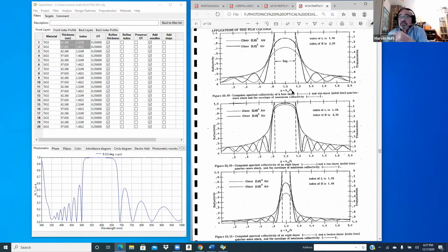We're saying that it doesn't matter, just like the quarter wave layer is a symmetrical V like this, one quarter wave. 2 quarter waves is like this, okay, symmetrical around G equal to 1. So this is really phase, okay? Because the phase is 90 degrees times G, lambda 0 over lambda, times the number of quarter waves. That's the phase. So this is phase.